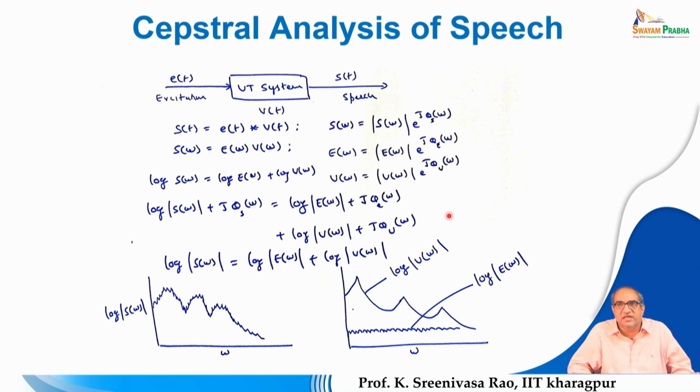That is because the coefficients mostly capture the characteristics of the vocal tract system. That is what we have observed. Whatever is not captured from the vocal tract system is represented as the error signal. So the error signal can be viewed as a kind of excitation signal corresponding to the given speech frame.